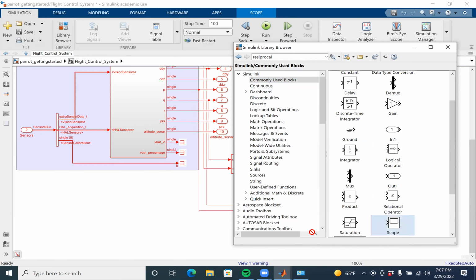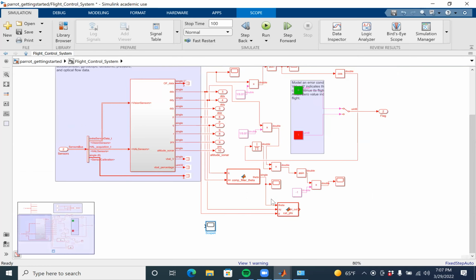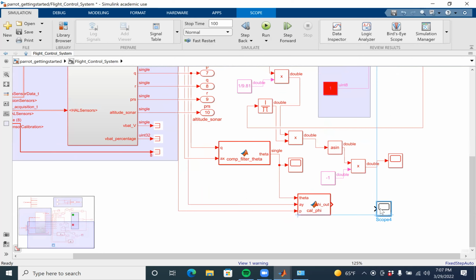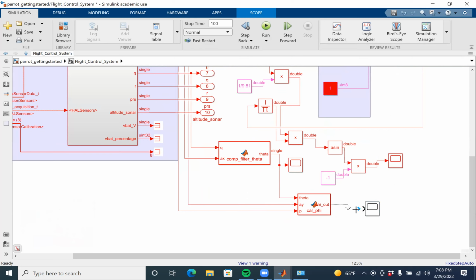The reason I wanted to show you this is because if you use function, implementing the PID control is super simple. Otherwise, you'll have to create those blocks and do it, right? Now, what you can do is just go here inside and add an error function and connect this to the mixing block, which is on top.